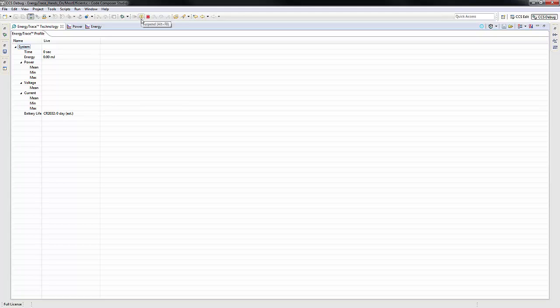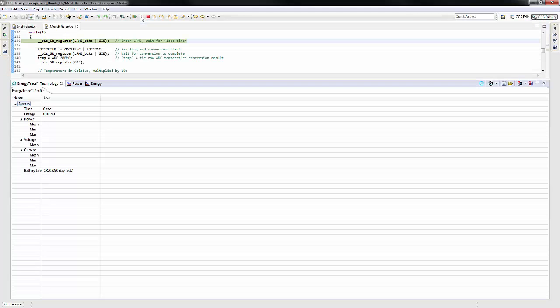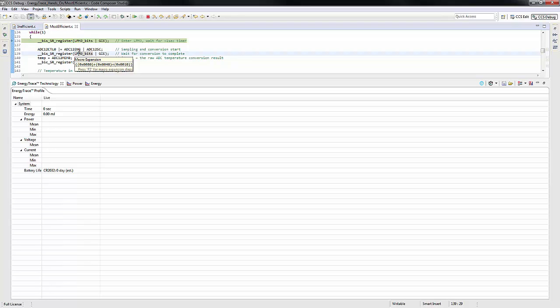So I want everyone to pause your application for now. Just suspend it. And if you remember correctly, in the first few slides, the debug communication layer affects the power consumption, right? But if you do this in free run mode, it puts all of the JTAG pins into a high Z state.